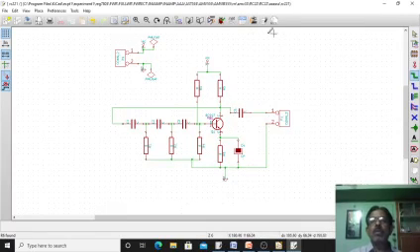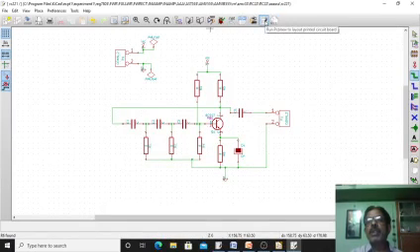Then you can give the name for this. This is the power supply connector, and this is the output connector. You can give the name also. Then next is PCB. So the schematic is over. Now I want to take this to the PCB layout part and draw the tracks. For that you have to click here, that is run PCB new to lay out the printed circuit board.